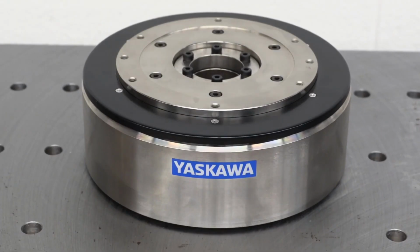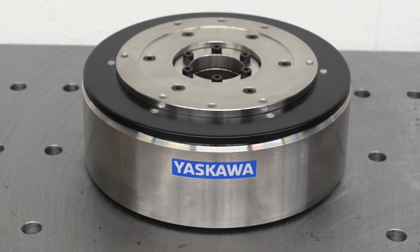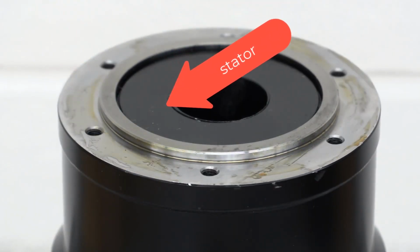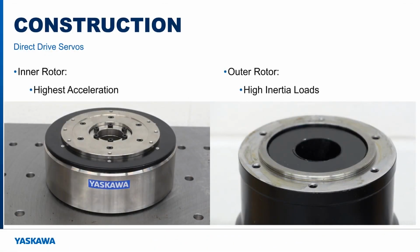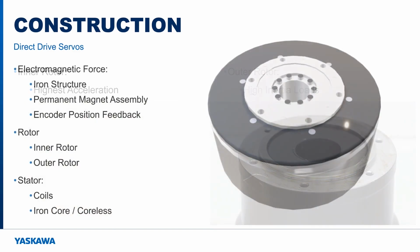This is inner rotor with stator coils on the outside, and the opposite configuration is outer rotor with the stator coils on the inside. The inner rotor configuration is capable of the highest acceleration for a given motor size. Outer rotor means the motor has a higher moment of inertia, better suited to control high inertia loads.